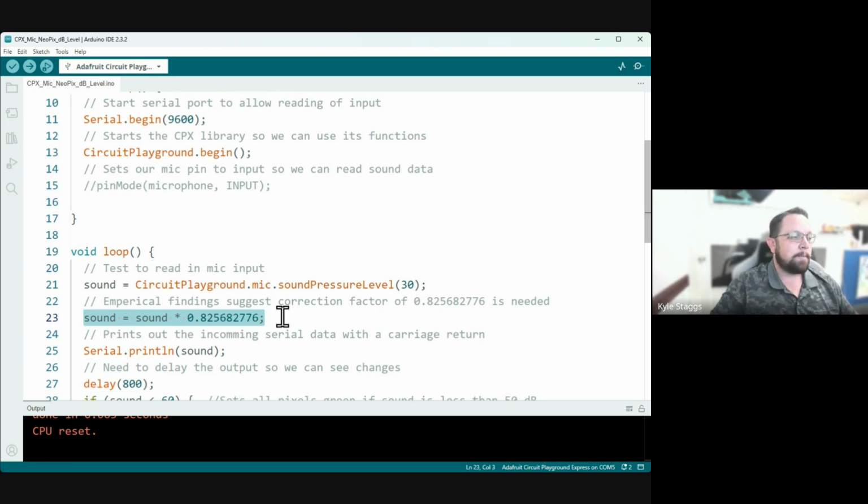So that's why these things are important, because if I could speak at 120 dB, I could throw people off of mountains at will, believe me. But that's clearly not a thing that's happened. The TV didn't go crashing through the door as I spoke to the Arduino. So we need to understand realistic parameters and when our sensors are giving us complete nonsense. And that's why knowing something about the range of output I should see is important. So that's why it's very handy to have some of that background knowledge in hand.